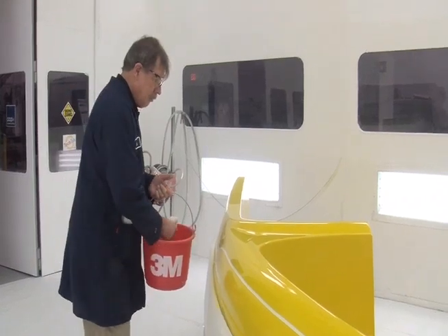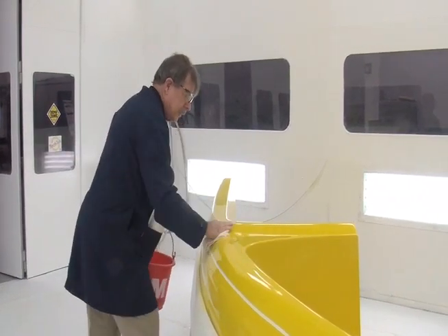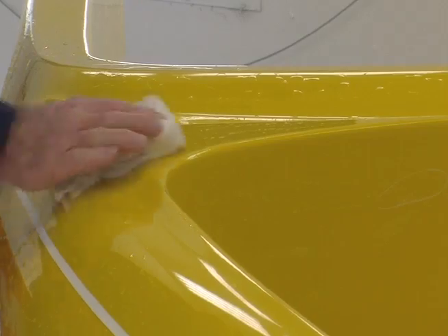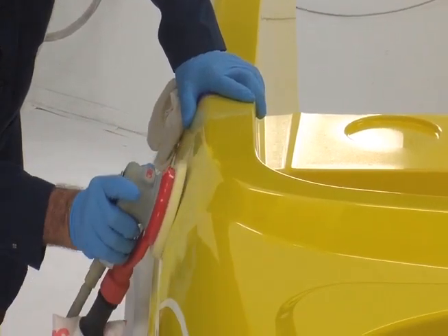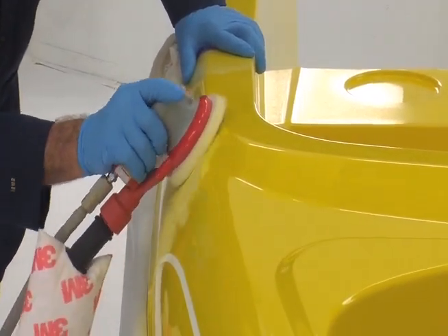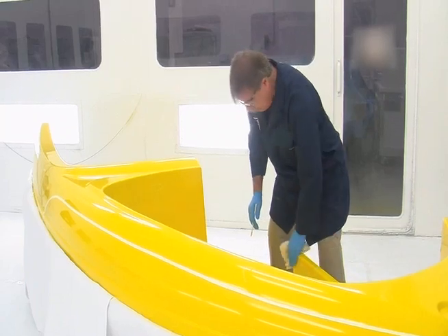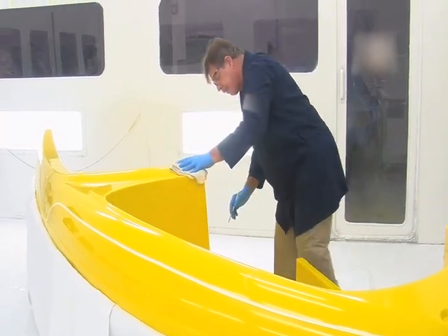Consider washing minor issues such as stains and discolorations with soap and water. If the defect is still visible, repair is still needed. However, repair may only require light sanding and buffing without respraying gel coat. Is it repairable? What's the extent of the repair needed?